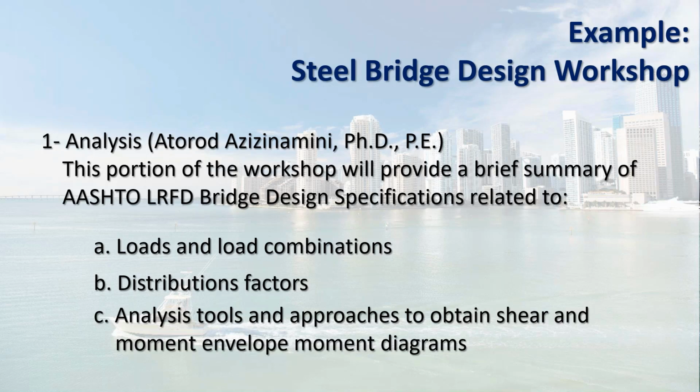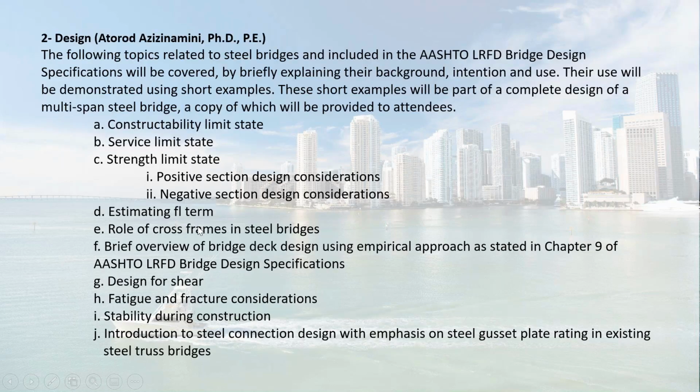in the AASHTO LRFD bridge design specification related to steel bridge design, for example covering the load combination, distribution factor, analysis tool, and many other details like, for example, the constructability limit state, service limit state, the strength limit state, estimating FL, and a bunch of other information that you really use in the design.